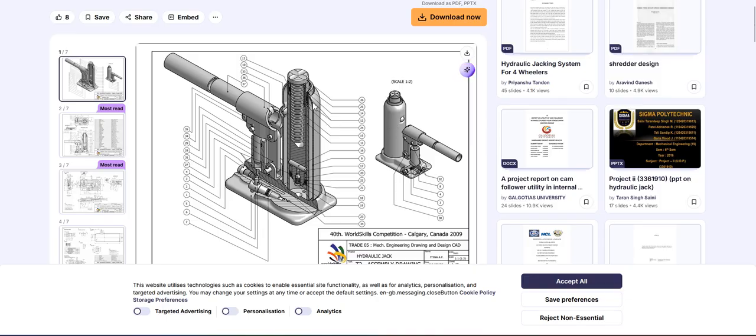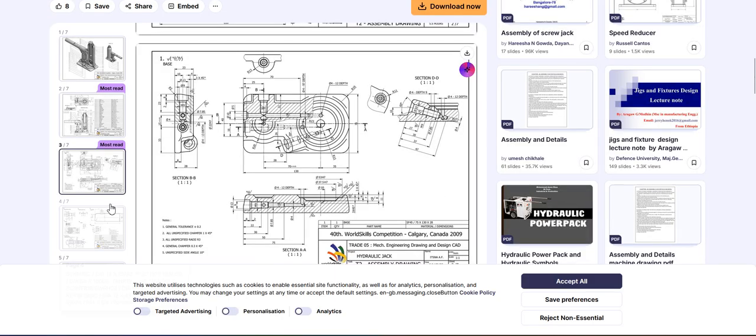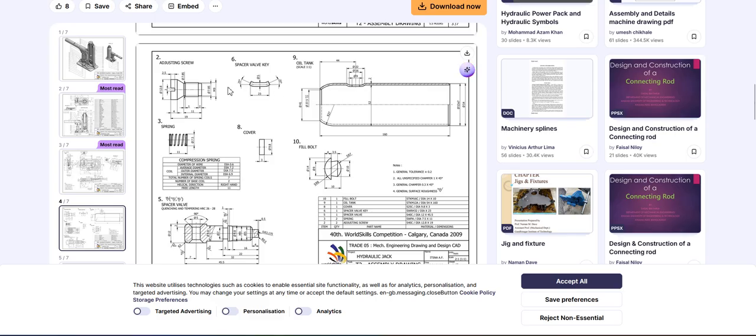This cylinder is going to be done by sheet metal working, using the deep drawing process. Then we're going to have the internal part inside, which is going to be welded at the end, because you can see it has two walls with a cavity within to allow the hydraulic fluid to run between them. You just need to go through the slides to understand the names of the different parts and how they were made.